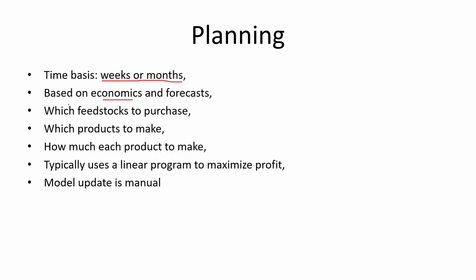And then they will do the optimization using the linear programming that we have seen in meeting number 2, right, where we touched on linear programming, where we did the exercise on refinery planning. So they can tell which feedstock to purchase, right? Is it crude 1 or crude 2, and which products to make given the constraints of the plant that we have, because we cannot use double of crude 1, so they are constrained to obey, and they will tell how much of each product to make.